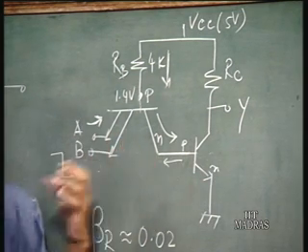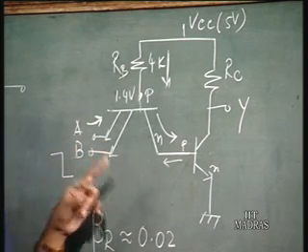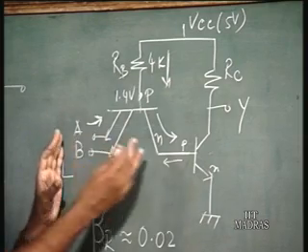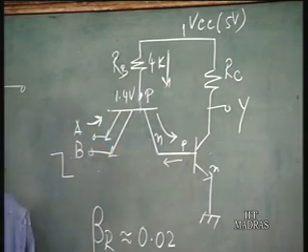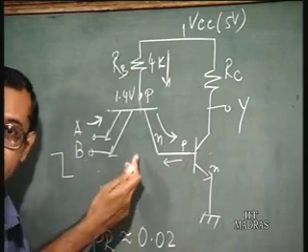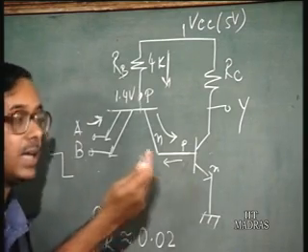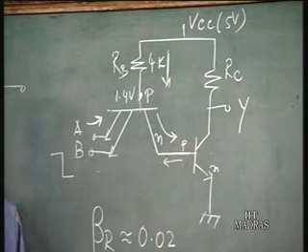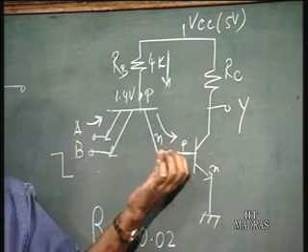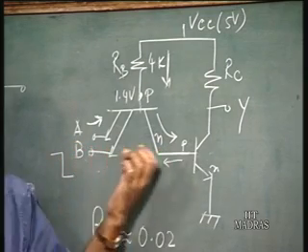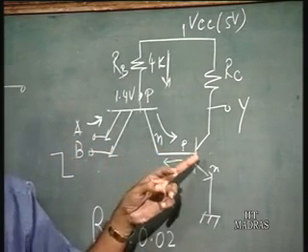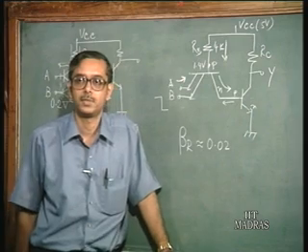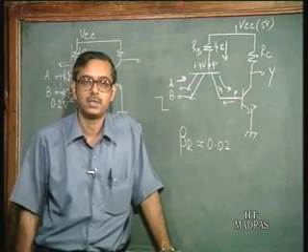So you see, when you compare with the DTL circuit, this is a similar situation. As I said, this circuit looks similar. Basically, you have converted 3 diodes into a multi-emitter transistor, but the advantage is the transistor action here, and this transistor, by its transistor action, actually provides a very large current to remove the base charge of the output transistor when that transistor is to go from saturation to cutoff. All right. So that is the major advantage of this circuit.